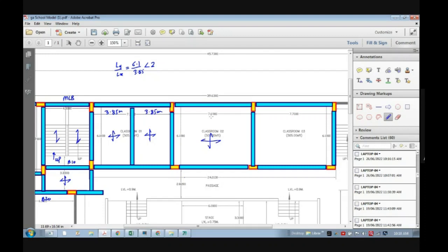So in that case, you can provide such bigger spans. There is no problem, and you need to design thick slabs. But as I said to you, there may be a possibility of a serviceability issue, or you need to give more thickness to such kinds of slabs. But I generally recommend for residential and public buildings, school buildings like that, it is better to keep the beam. See, in a classroom, the students are not looking at the ceiling always. Yes, the classroom is for training.